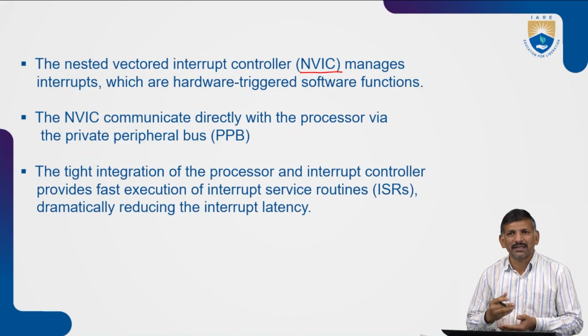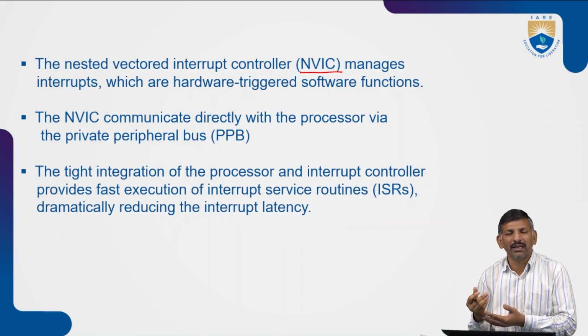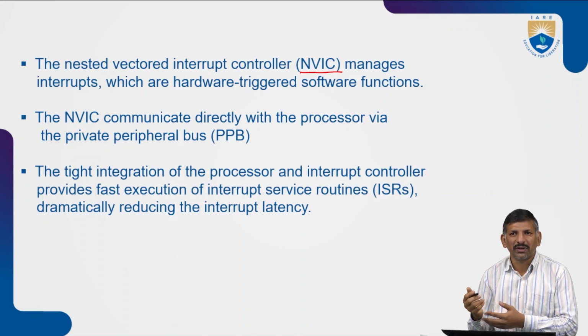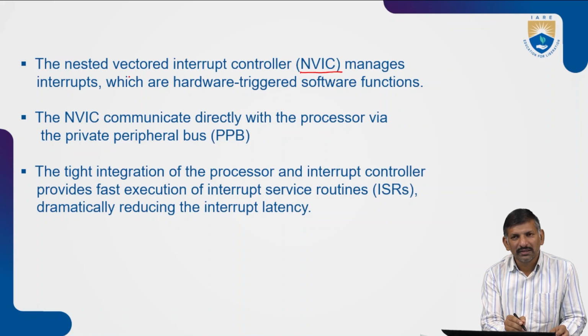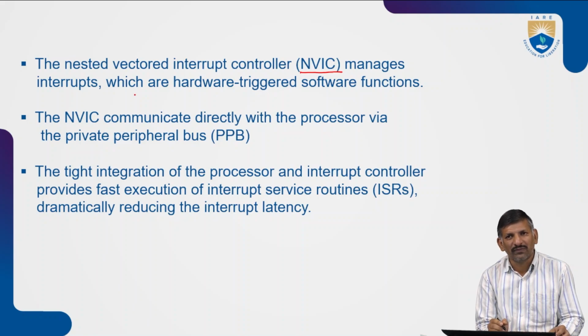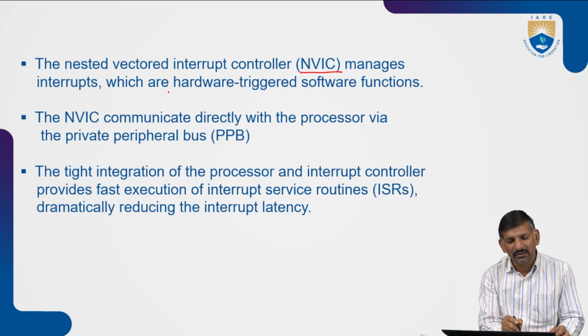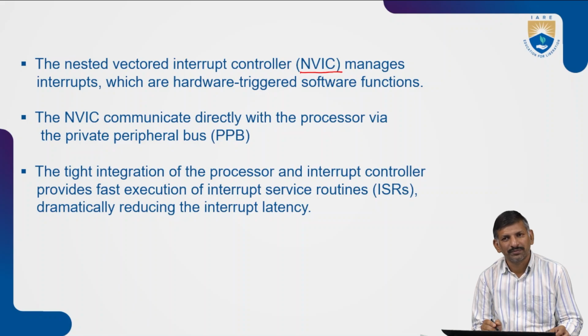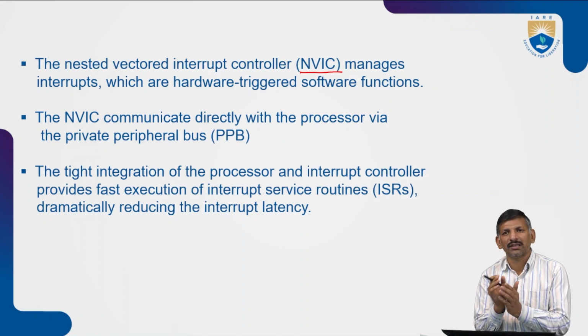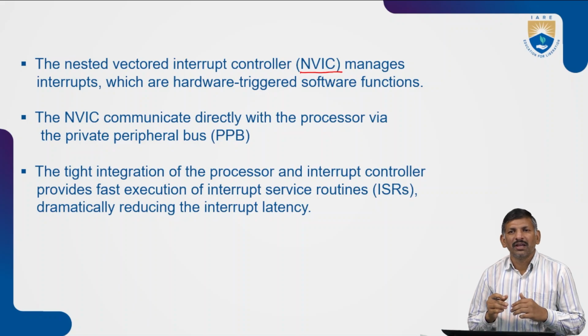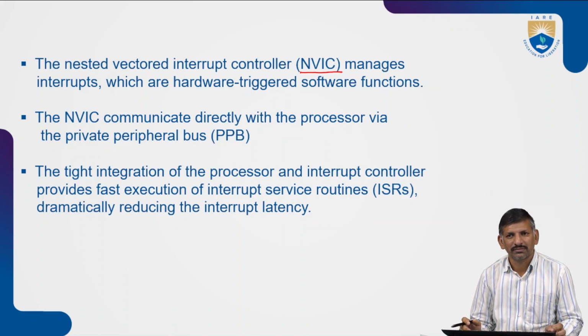As the interrupt latency, meaning the interrupt delay, increases, the task may be delayed, and we can miss the deadline. Missing a deadline may cause loss of life or property. So this ARM Cortex-M4F series processor architecture provides a tightly integrated nested vector interrupt controller. It reduces the interrupt delay as much as possible by efficiently scheduling the interrupts.